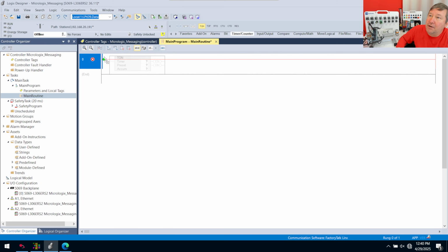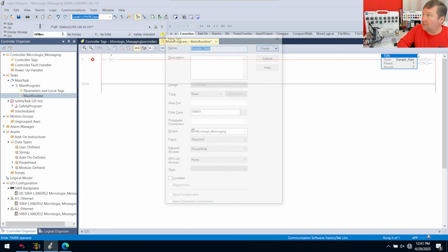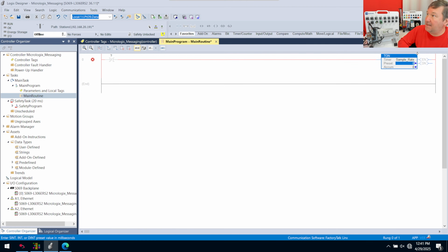And we're going to bring a TON down off the timer counter. Go to our favorites and go look for a 0 in front of it. And I am going to call this our sample rate. And then we'll go ahead and create that. And I'm going to make it 1000 for a preset, or 1 second sample rate. And then here we'll go get our sample rate.DN. And so all this is going to do is make this done true for a single scan every second.